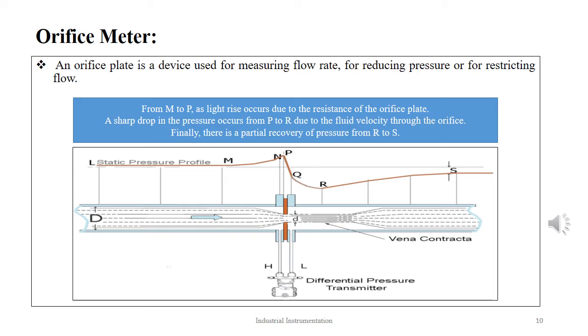The orifice meter, when installed in small to moderate sized pipes, is probably the cheapest and the simplest flow measuring device at present available for metering liquids, gases and vapors. It is not suitable, however, for highly viscous liquids and fluids in a pulsating or extremely turbulent condition.